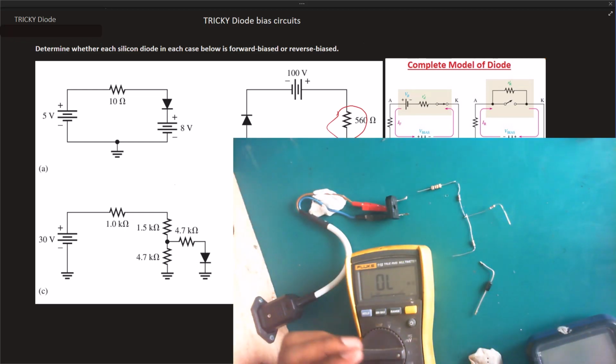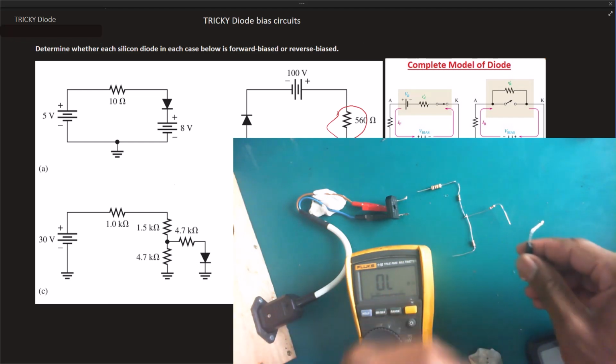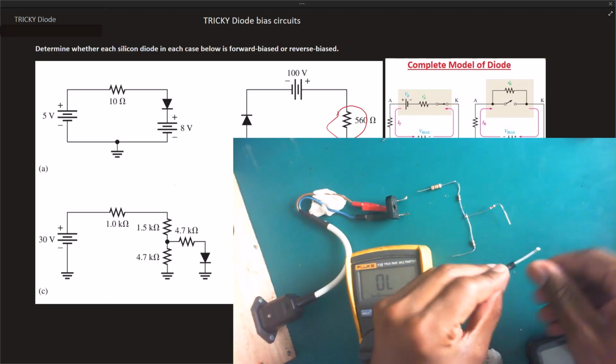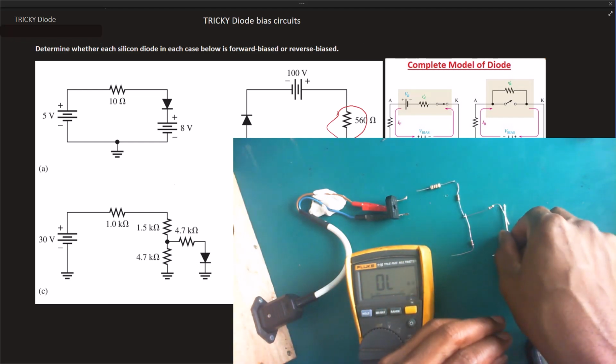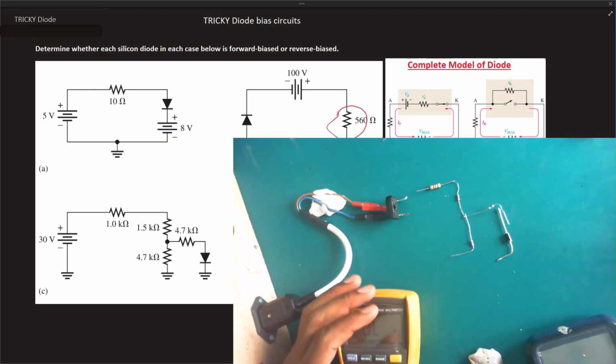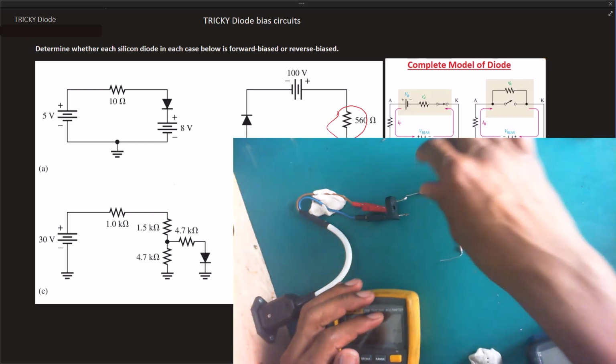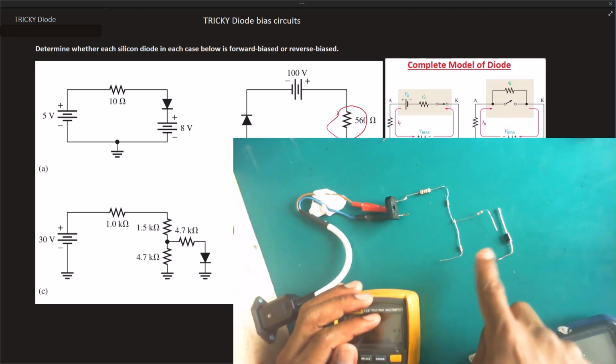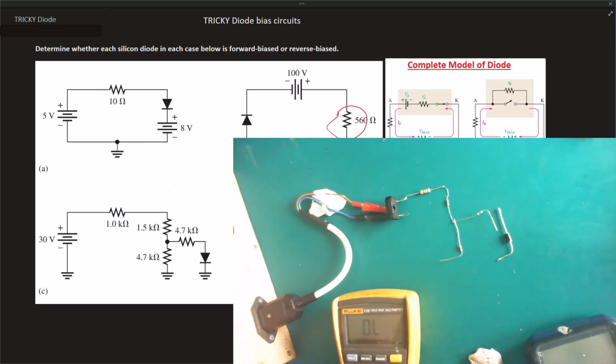So now what I need to do here is take my diode, connect the anode of it onto the resistor like this, and then connect these points together and tie my ground. And then we are done with our circuit. Then we can move on into testing.